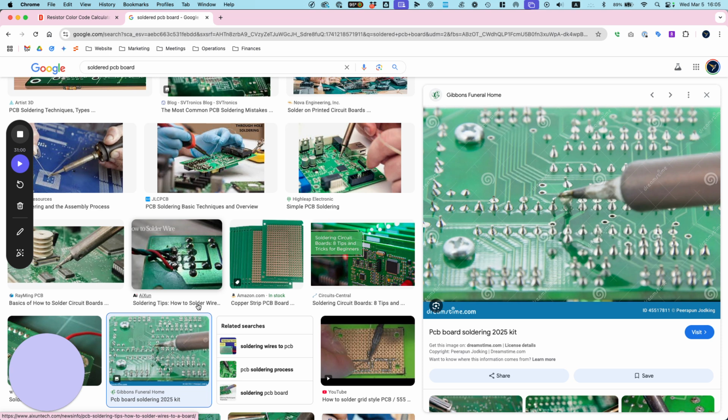All right, so I'm going to first desolder, because this particular example we need to remove something. So this is also a good demonstration. The solder sucker, do you still have it? All right. Can I actually demonstrate with this too? Is that okay? Okay. So there's two ways to remove solder from an existing component. We have a solder sucker right here, as the name implies, it's going to suck the solder out once it's molten.